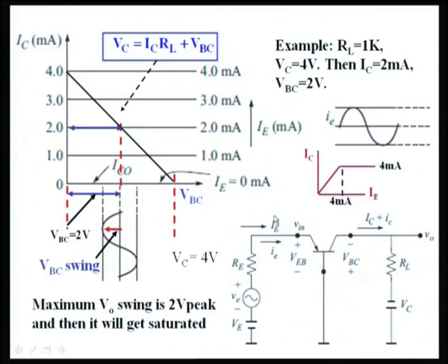So, the swing can be between 2 to 4 and 2 to 0, 4 volts maximum peak to peak you will get in this device. That is what I am trying to point out: the sinusoidal operation of the signal will stop when the amplitude of the sinusoidal signal reaches close to the supply voltage, or when the amplitude reaches close to that 0 voltage point. If there are two supplies VB on both ends of the amplifier, then you will have plus and minus upper limits.